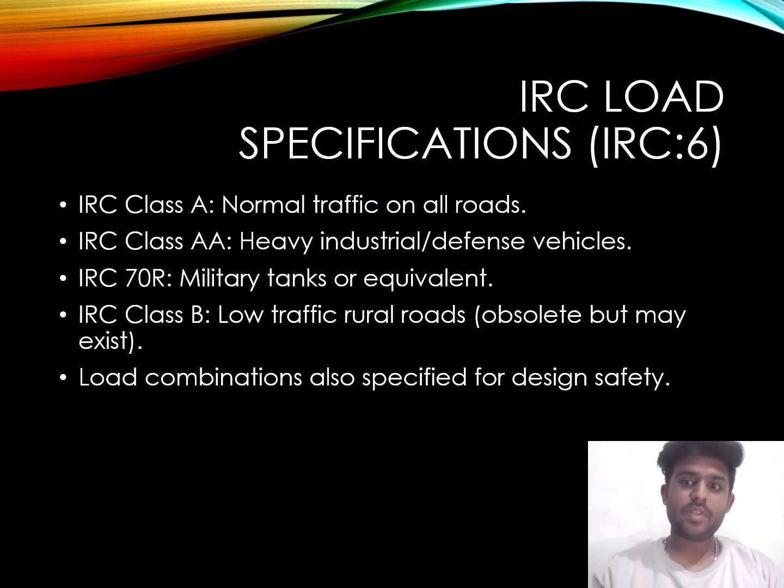IRC loads specification. IRC Class A, normal traffic on all roads. IRC Class AA, heavy industrial or defense vehicles. IRC 70R, military tanks or equivalent. IRC Class B, light traffic and rural roads, obsolete but many exist. Load combinations are also specified for design safety.